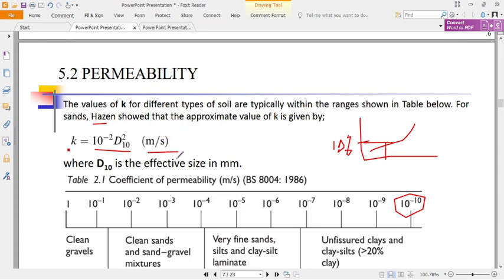Is that okay? So it also applies in stability analysis of earth structures. We shall look at that briefly in our next class. Stability of earth structures and earth retaining structures subject to seepage pressures. So if this is the head, times the unit weight of water, this will give the vertical uplift pressure, the water pressure, or the thrust. Is that okay?